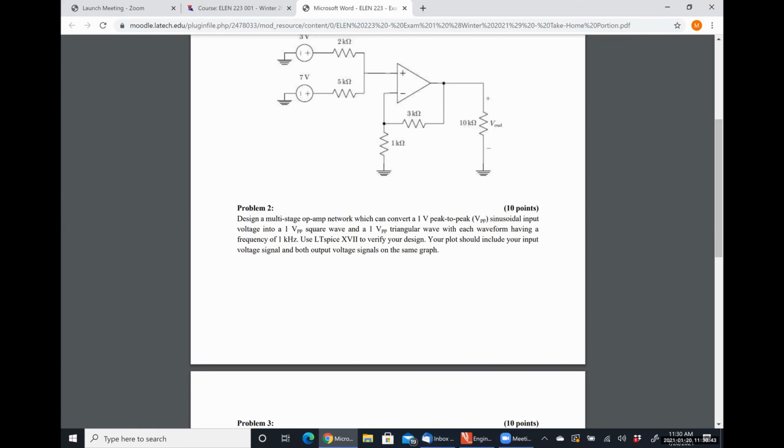So yeah, the only thing that you really need to pay attention to there is sizing your components in such a way that it allows time for it to discharge so that it falls down. It doesn't rise and then drop a little and then rise and drop a little. It should be going up, falling down. Yep, so you just need to resize your components to achieve this specific frequency.